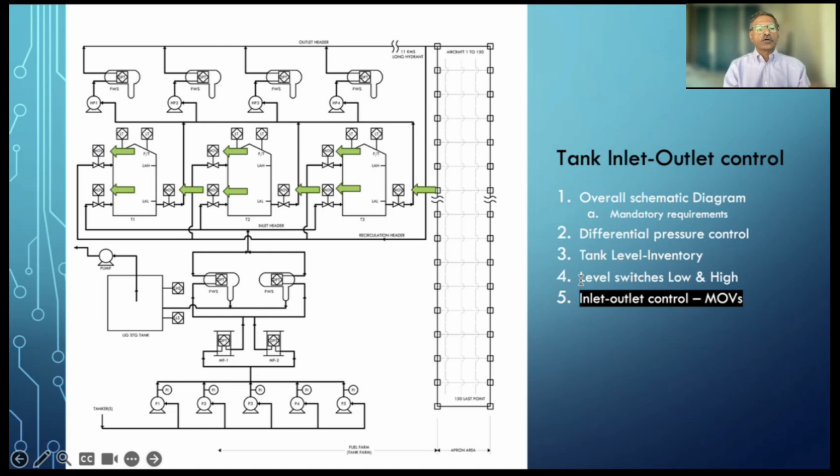The other one on the top of it is a recirculation. Say on the hydrant, you are pumping the product, and if suddenly one flight stops because it is full, the product is recirculated into the hydrant; it will come back to this recirculation line and go back to the tank. So on each tank, there is one inlet, one recirculation, and one outlet.